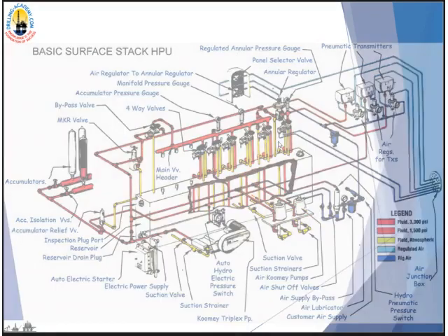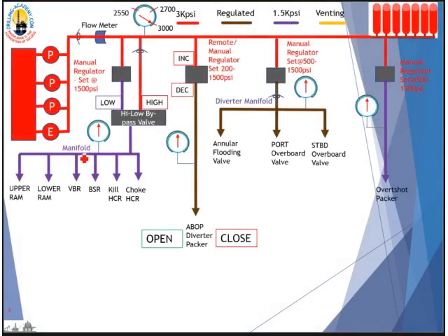From this busy diagram, I turn it into this diagram here, which is more organized, clearer, more transparent, easier for you to follow and to understand. You have the air pumps here, three air pumps here. They are the primary pumps, and the electric pump is the secondary pump. In some systems, you have two electric pumps. One is supplied from the emergency generator, and one is supplied from the main bus bar. All right, the one supplied from the main bus is primary, and the one supplied from the emergency generator is the secondary.